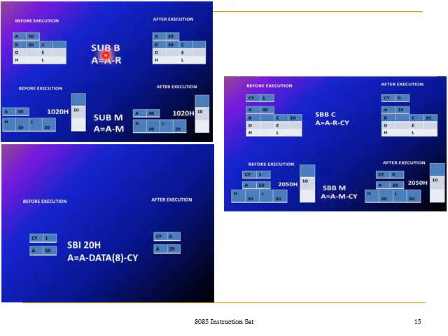So the first is SUB B. What it is going to do is subtract the B register content from the accumulator content. Here the register is the B register, so the accumulator content is subtracted with the B register content. After subtraction, the result is going to affect the status register or flags in the 8085 microprocessor, right? So the values 50 and 30 are chosen.